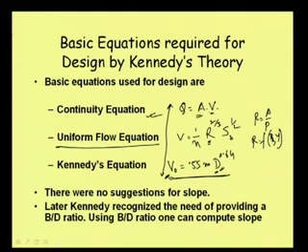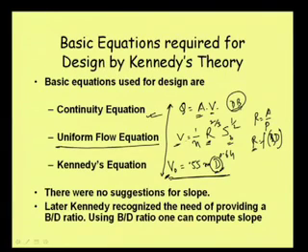Then from the area of the canal, the area is again a function of b and y. Y means the depth I am talking about, and here of course we are using the symbol d, so in this place also I can write d in place of y. So the depth is already known. So b we can calculate. Once we get d and b, then using d and b we can calculate R. Then of course, the bed slope will be known to us. For that bed slope, we can now calculate our uniform flow velocity V.